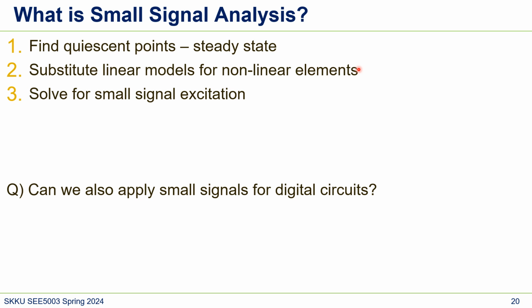And when we think about CGD, the capacitance from gate to drain, that value changes depending on what region the MOSFET is in, right? So if the MOSFET's operating region changes every time, it's really hard to model, because, as I said, capacitances are changing depending on the region.